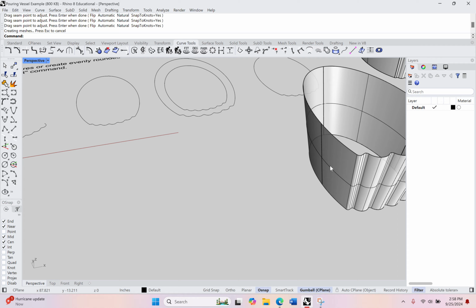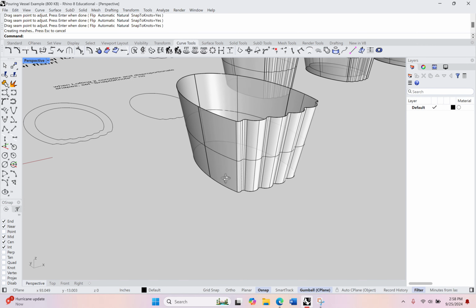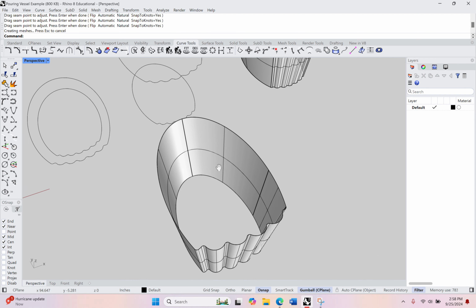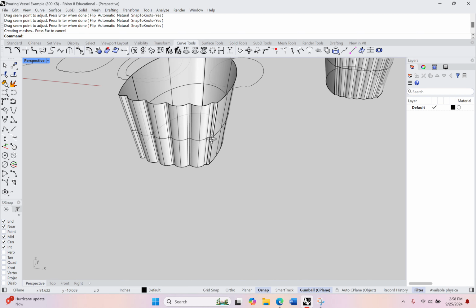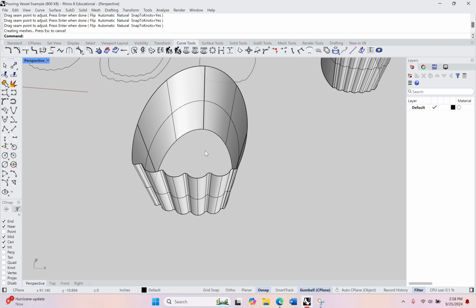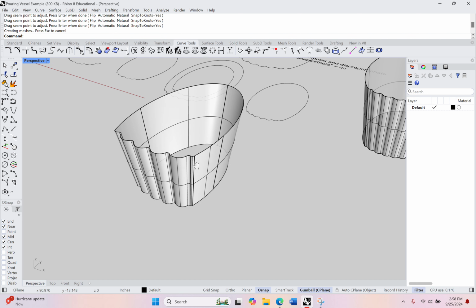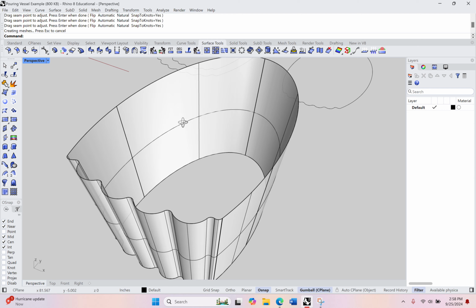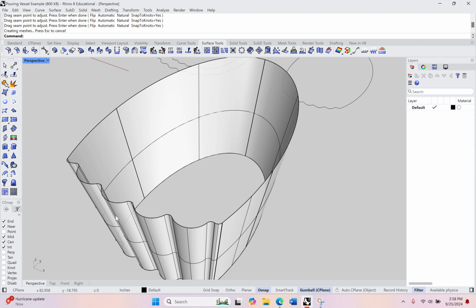Okay, so if you're trying to loft two shapes to make a surface, and it doesn't look quite right at first, maybe just tinker with those arrow indicators to see if a little change can make some difference. In this case, it did. Sometimes you just don't know until you try. So I've got this surface now, which is great.